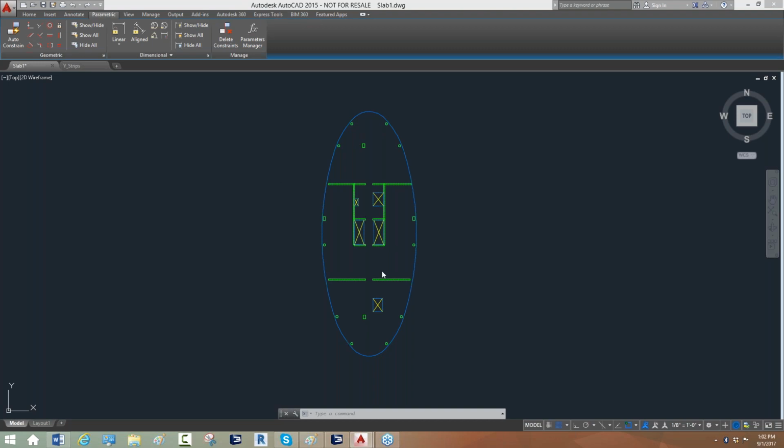direction support lines. And just arbitrarily, we're saying that the X direction is quote-unquote banded tendons, and the Y direction are uniform tendons. So in terms of being able to model that inside of ADAPT-PTRC, it really doesn't matter. You just model a strip or a design strip, and that could be for a banded line, it could be for a uniform line. The program gives you the output in both forms in terms of total force, number of strands, or the force per width of the tributary in that program.